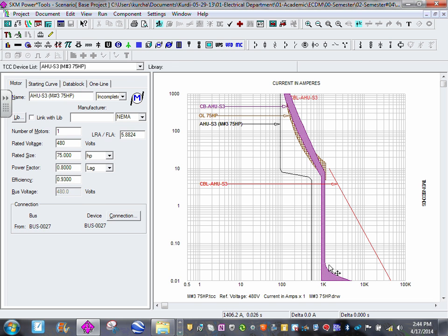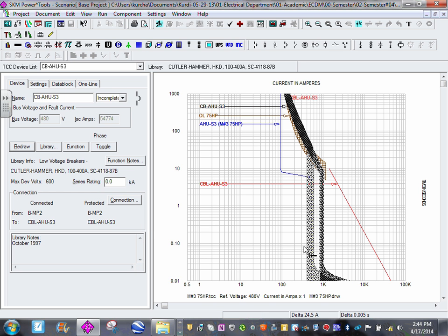And if you guys remember the instantaneous right here, this is the instantaneous circuit breaker. What I suggest, long story short, if you're dealing with 3-phase motors, always ask for an instantaneous adjustable circuit breaker. They're perfect. They're molded case circuit breakers, still cheap. The only thing you can adjust is the instantaneous.